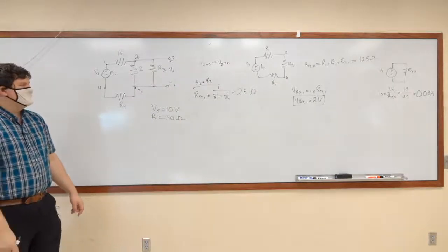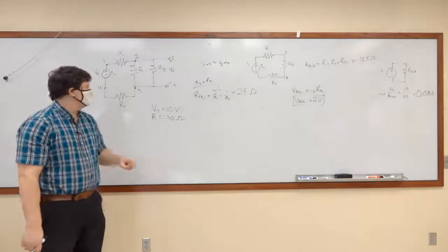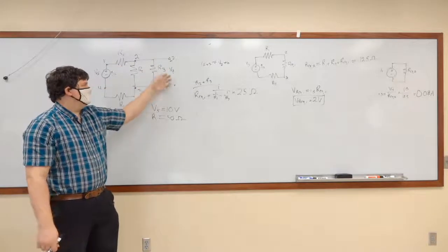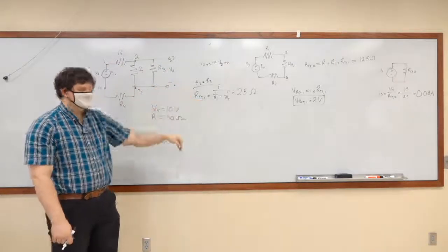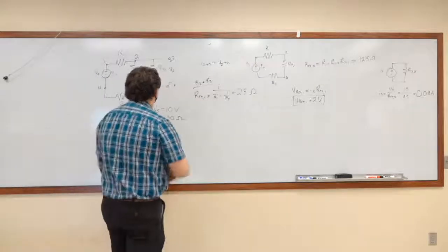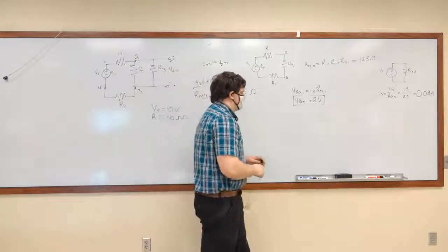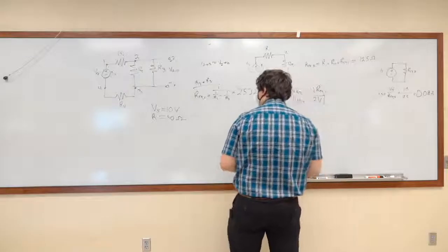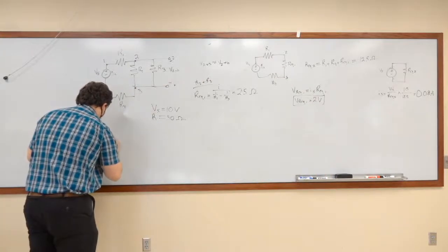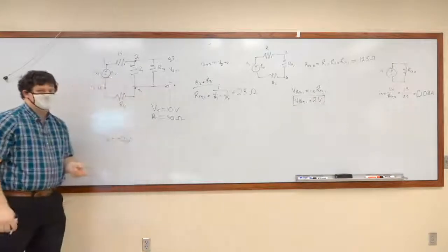Okay, now we know 2 volts. In this configuration, the open circuit voltage, which is the voltage between 2 and 3, which is the voltage between A and B, which is VA, is equal to 2 volts. Well, VA to B. Okay, so I'm gonna go ahead and write that down. I'm gonna call it VOC equals 2 volts. Stands for V open circuit.